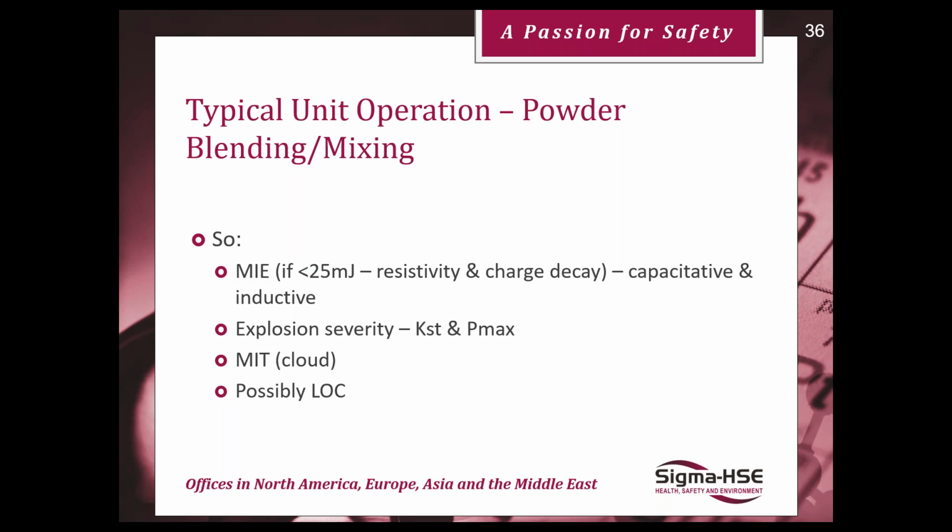Within a mixer or blending operation, we will be creating dust clouds, so the minimum ignition temperature is important to know. We can relate this, for example, to the bearings or the agitator mechanisms, making sure they don't run too hot and don't reach temperatures in excess of the minimum ignition temperature. Or we could perhaps put some inerting in, or operate under vacuum, or where liquids are concerned, cool the blender or mixing operation down to prevent those vapors or dust producing a flammable atmosphere.